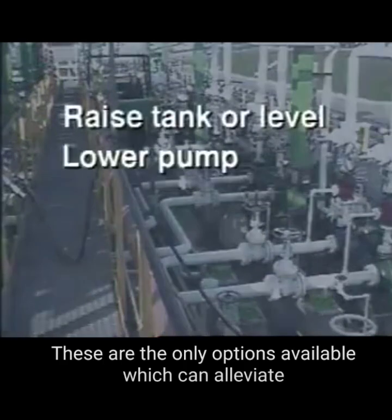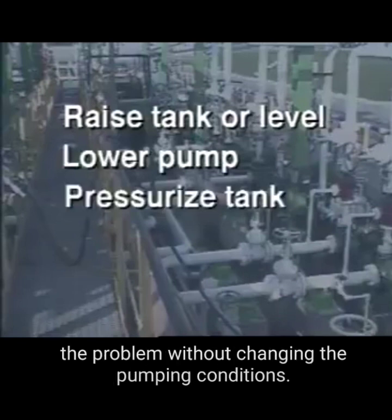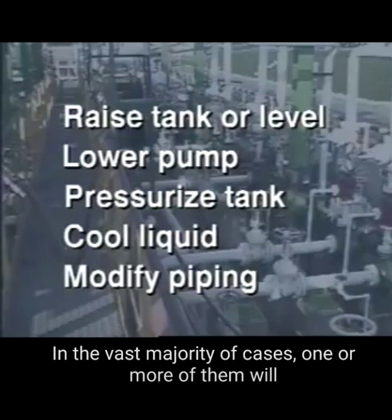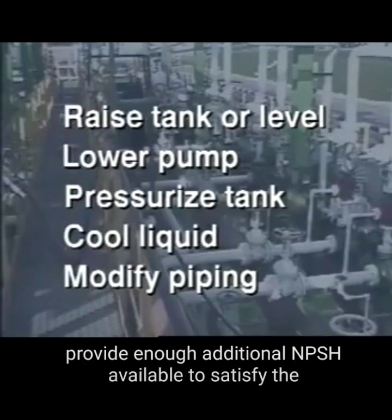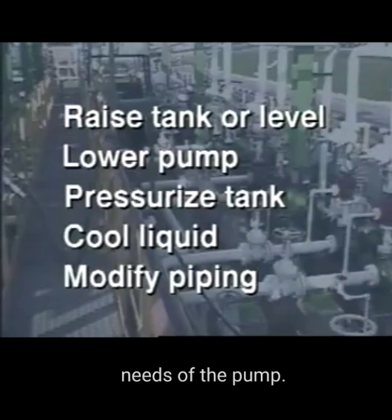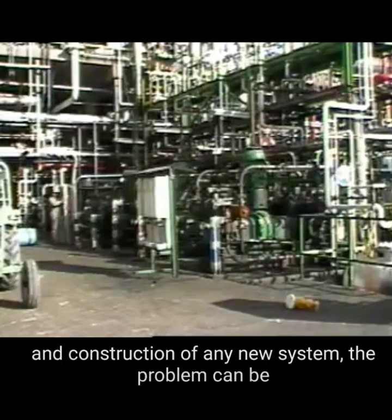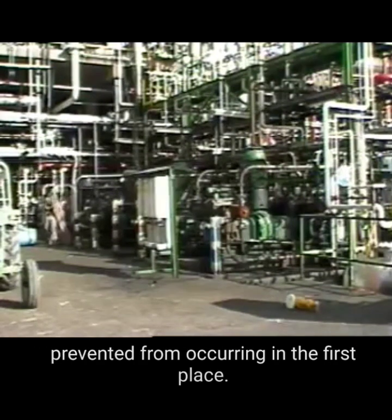These are the only options available which can alleviate the problem without changing the pumping conditions. In the vast majority of cases, one or more of them will provide enough additional NPSH available to satisfy the needs of the pump. By taking these same factors into account during the design and construction of any new system, the problem can be prevented from occurring in the first place.